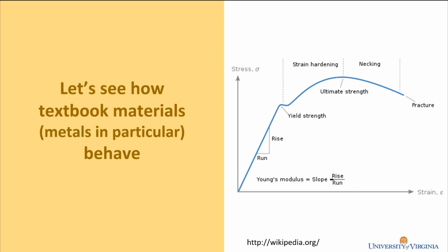And then stress, the vertical axis, is just force over area. And the important thing to know about stress is that it's the thing that actually leads to a part failing or breaking. So as we walk through this diagram a little bit from left to right, it says that as you strain a material, the more you stretch that material, the stress goes up.